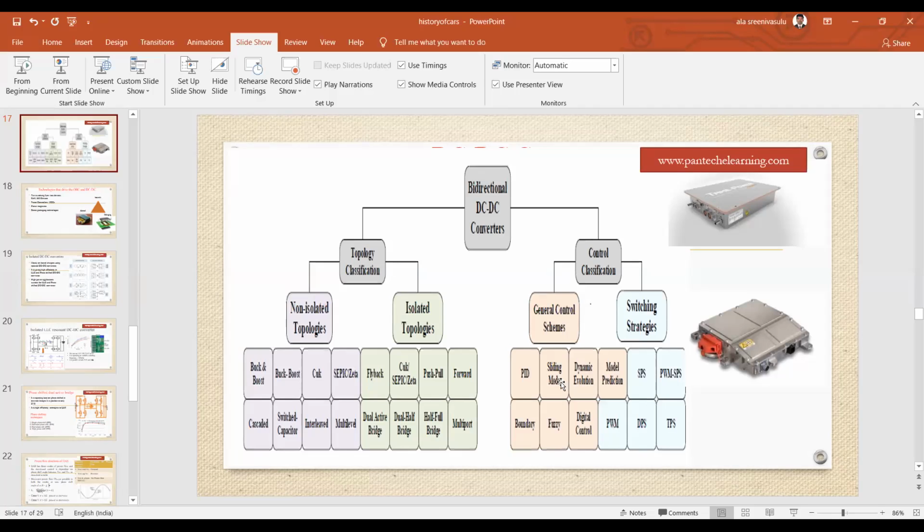In the SIL test, they use embedded C, and by using the embedded test they analyze ten different cases, ten different ways they will test. Then, if the model in the loop and SIL test are satisfied, we shift to the hardware in the loop. In all three tests, MIL, SIL or HIL, we need to get the same required output. Otherwise, if any mistake comes, we need to verify again with the model, SIL or HIL. The three steps are there. If we are satisfied with these three test cases, then we can go directly with the real-time product. All the companies do this.